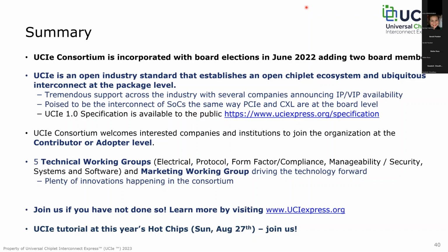UCIe-A and UCIe-S chiplets, can you connect them together? No, you cannot. There are multiple fairly important differences between the two different types of UCIe flavors, the advanced and standard. There's significant differences in beachfronts, as we showed earlier.